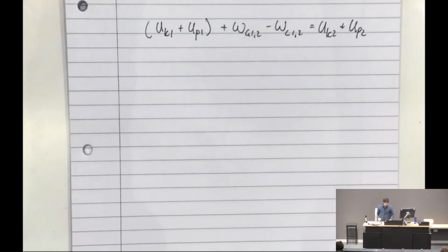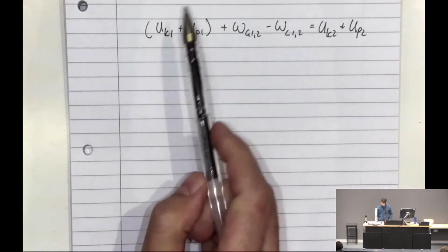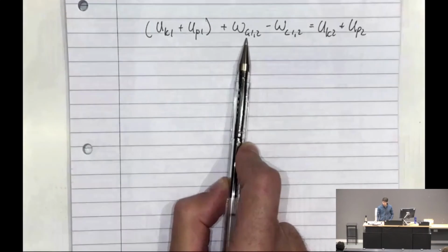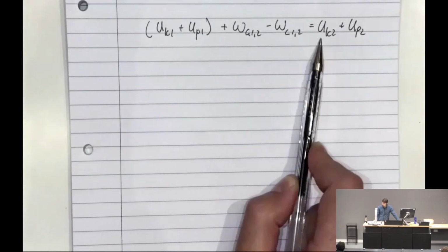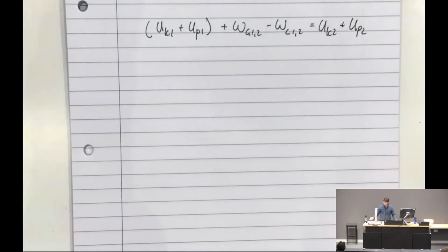All right, so when we use the conservation of energy equation, which is the mechanical energy at point 1, plus the work gained minus the work lost equals the mechanical energy at point 2. We can see that mass 1 is moving, but it does not change in height, meaning that its potential energy is not changing. It's got constant potential energy. So the change in potential energy for mass 1 is 0. There's no change. It's the same potential energy. Its kinetic energy changes because it's increasing in speed, thus its kinetic energy is increasing. So there's a positive addition of kinetic energy.